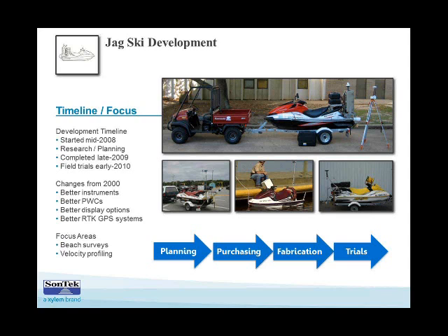Review bathymetry soundings. So you can see soundings around the tracks now. And then kind of clean it up a little bit and look at the interpolated bathymetry of the flood shoal. You can then also look at velocity measurements.